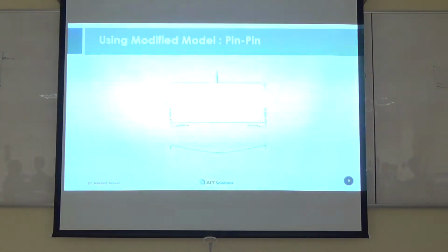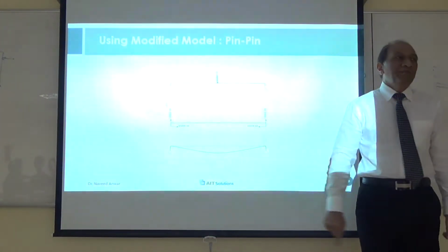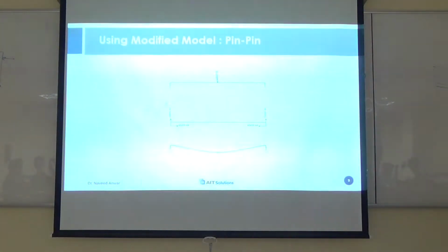Right? So we can start to see that we cannot treat these separately, and we will see that this stiffness is not only the bearing stiffness, but also the pier stiffness and the foundation stiffness. Everything is holding it together because the displacement at the top of the pier will cause bending in the column that will move the foundation, which will move the soil. So this horizontal support is coming not only from the bearing, but everything below the bearing, because the bearing is resting on something. It's becoming a little bit more complicated now.